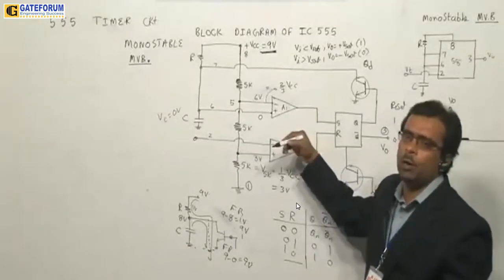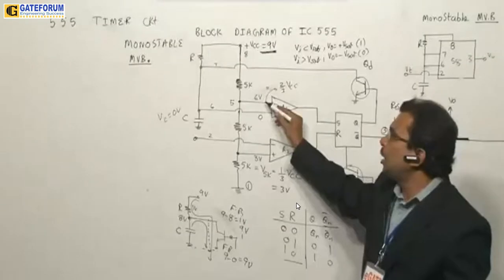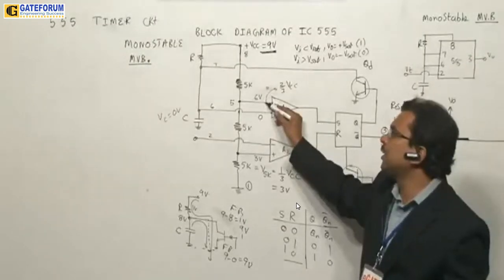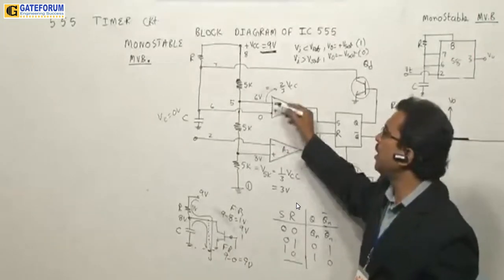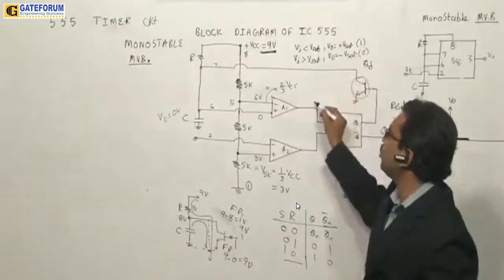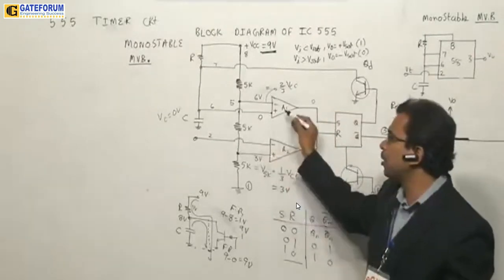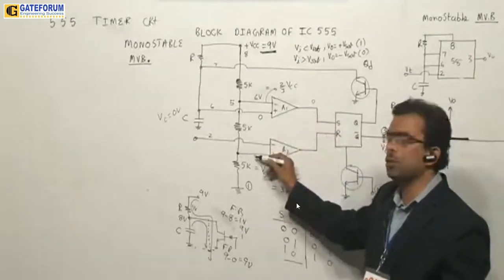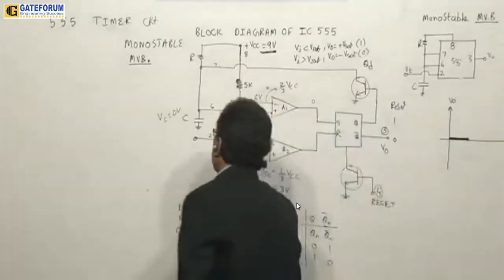Till now, how we have studied, let us stick to that point only, even though it is observed here reversed. What I understand is input is at 6 and reference is at 0. Input is greater than reference. If input is greater than reference, then the output should be 0. So the output of this comparator is 0. At this situation you check, you did not give any trigger.